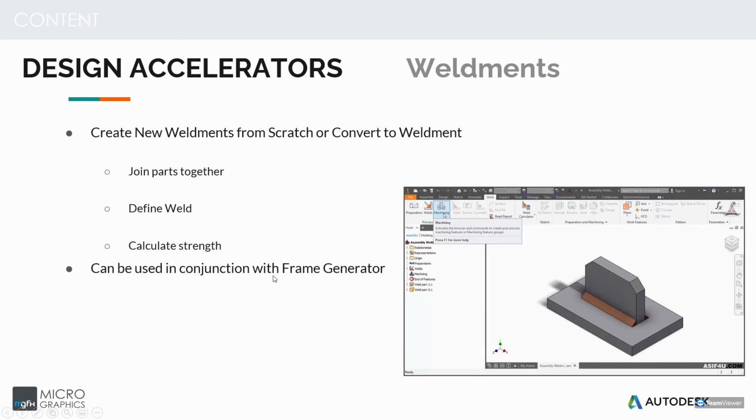This can also be very powerful if used in conjunction with frame generator. If you think how time consuming it is to make a frame from scratch, maybe some frame to fit on some sort of trucking system or stuff like that, you would find that you'd have to measure each point manually and then cut off or miter them and then go in and put in where you'd want to weld it in your drawings perhaps. Whereas with this, you can do it all in one shot using frame generator, convert to weldment, and simply insert your welds from there.